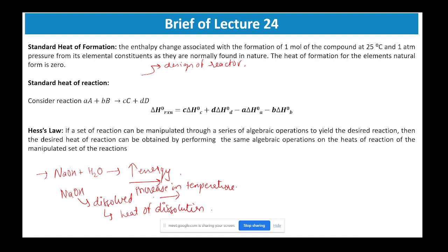So for example, if there is heat liberated during the system, then we need to take out the heat from the system, because otherwise the temperature will rise, and the temperature can go up to where the reactor pressure will be affected such that it may burst. Or how much energy should be supplied.